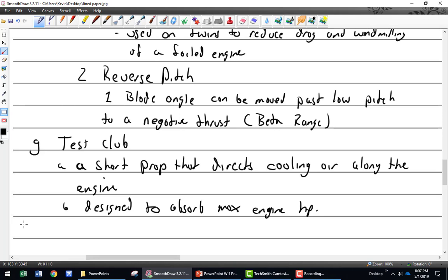Oh, that's really weird. What do you suppose it is? Well, double check the mags. Oh, mags are great. I mean, you troubleshot this thing forever. And I said, well, I'll come down and take a look at it. Go ahead and start it up. And the thing just shook like crazy. I'm like, shut it down, man. Could you try measuring the prop? They built it offset by some crazy number. It wasn't like a quarter inch. It was like 1.5 inches or something. The hub was offset. And you could even see it when you walked up to it, it's not even centered. So I sent it back.